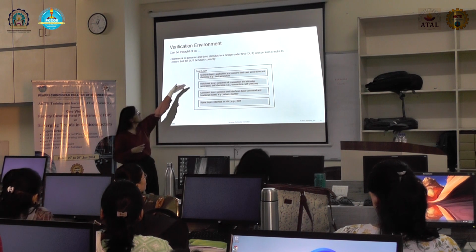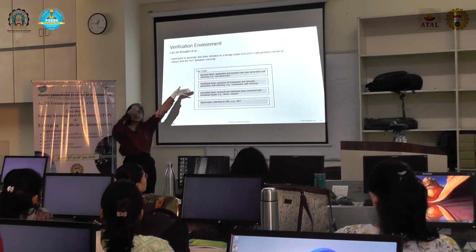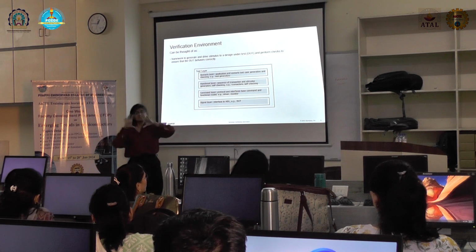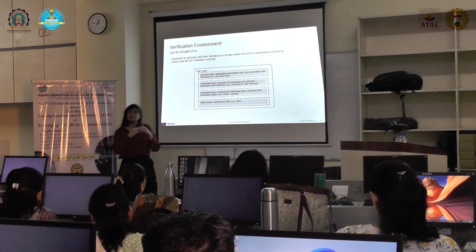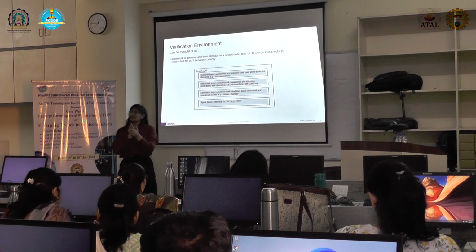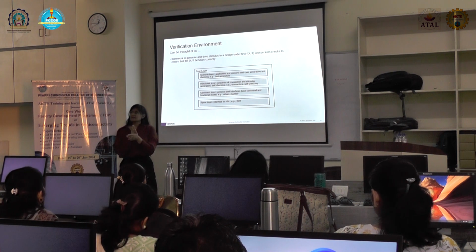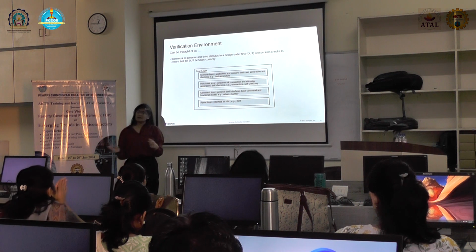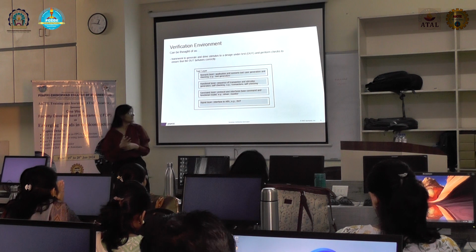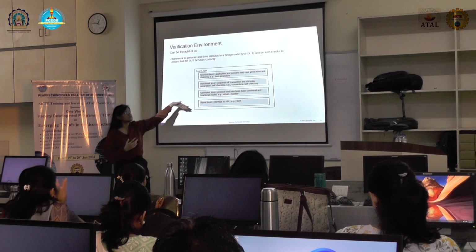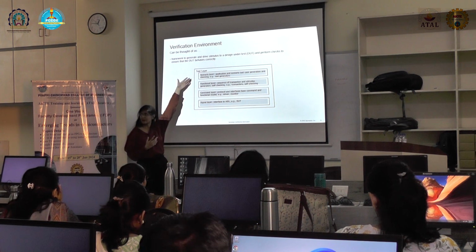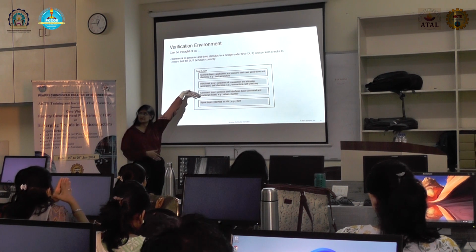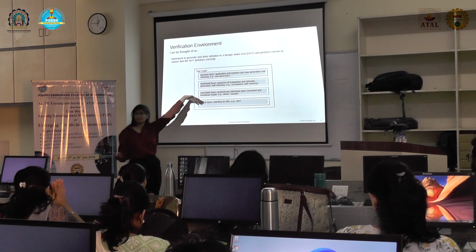testbench architecture. And the scenario level is the most abstract level, which is part of the planning of the testbench architecture. In that, there are multiple sequences that we can use, like back-to-back read, write. In that case, we define a scenario which will have multiple sequences, read and write sequences, and we can execute it in a single testbench. So that all comes into planning of the testbench architecture and environment. We code this according to the language that we are using, if it is SV or UVM.